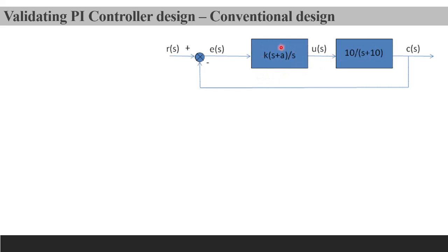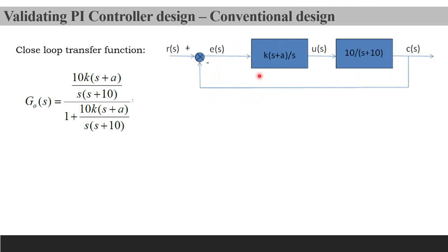So I'm using the PI controller here. If this is the PI controller, it would be cascaded and we have unity feedback. So let's simplify the whole transfer function for the closed loop ratio. This is how we find the closed loop ratio: g of s times gc upon 1 plus gc and gs, and we solve it out and we have a second order function like that.